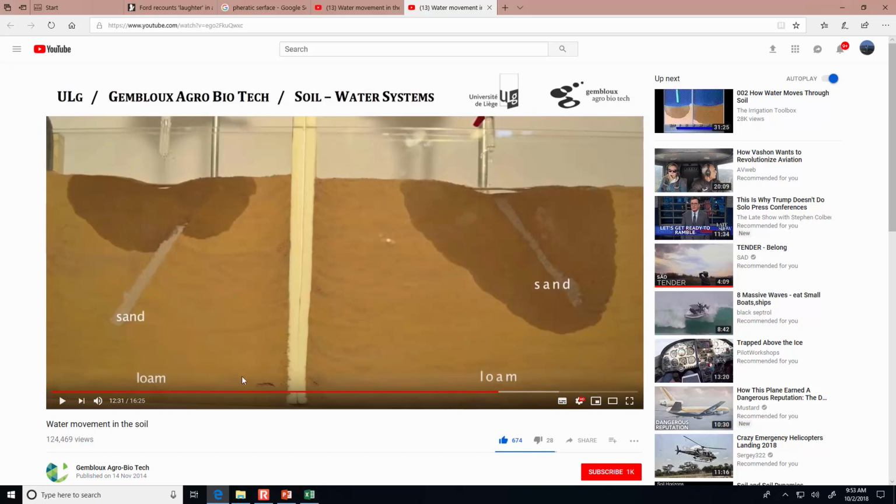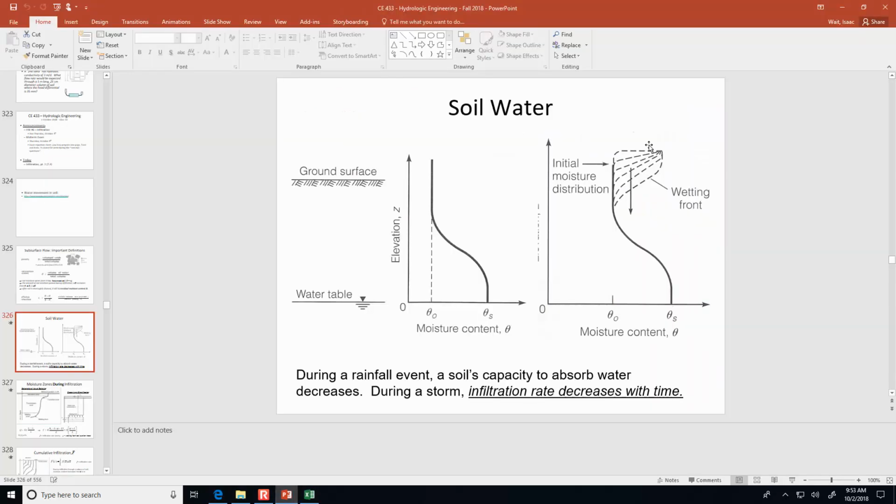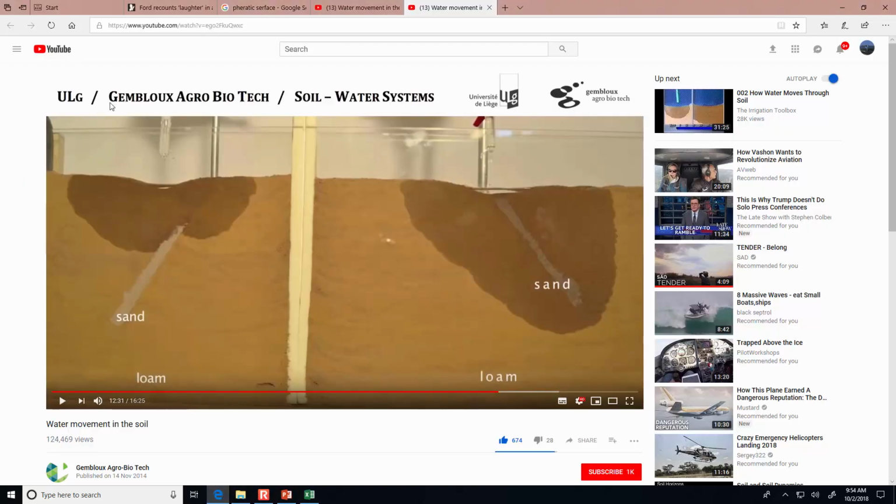But that's an important point, and I also wanted to tie it together with these figures that we're going to look at. These figures seem abstract when you just see them for the first time and you're not able to relate them to this visual representation of the water penetrating down through the soil. What we're seeing is the wetting front go downward and outward because of gravity and because of the suction/tension within the soil. Those are the two things that are bringing the water down. But then there's the difference between full saturation and just an increase in moisture.